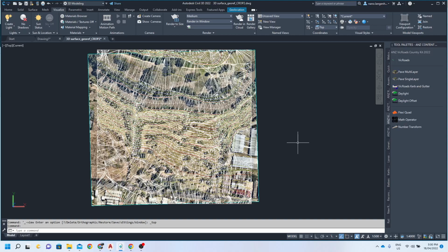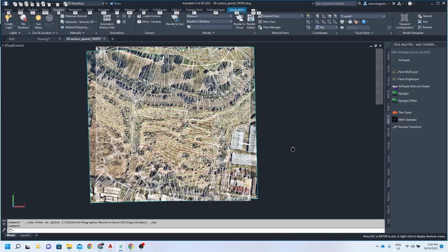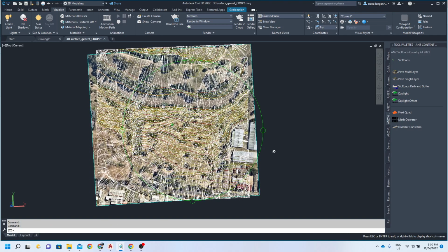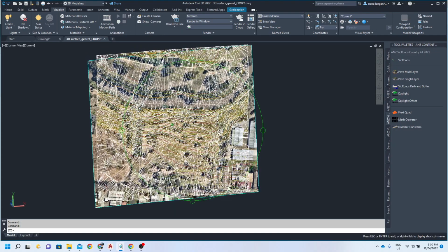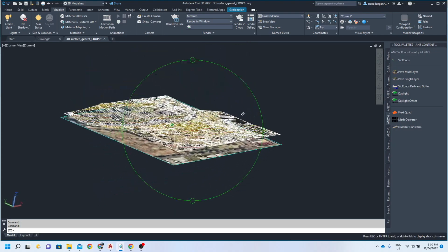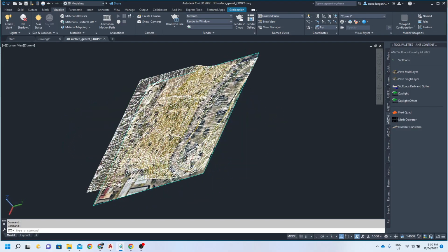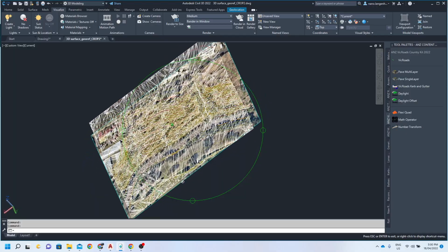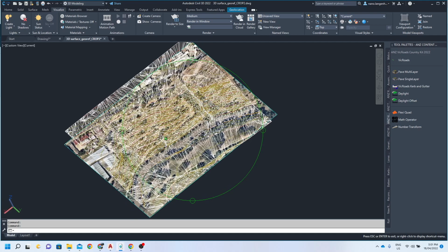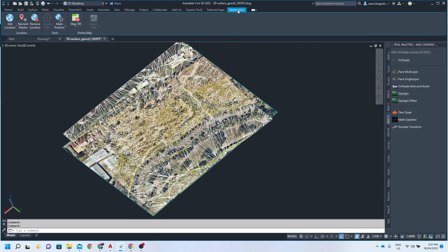Okay, what we've got here is a Civil 3D surface. I'm using Control Shift and the little mouse button to orbit around it. And underneath that, we've just got an attached aerial image. That still seems to be the best one to bring in an aerial image. You don't seem to be able to use a clip of the Bing maps in this circumstance.